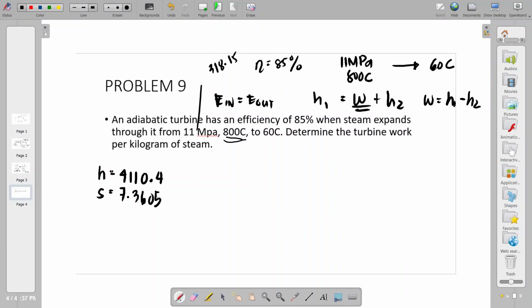Okay. Ngayon, naging 60 degrees Celsius daw siya. Okay, check natin sa 60 degrees Celsius kung anong nangyari. Table 1. Kung naging saturated temperature ba siya. Ang S dito ng 60 ay between. Ang SF niya ay 0.8312 at SG ay 7.9096. So, ibig sabihin, si state 2 ay naging mixture kasi in between siya nito. Okay? So, hanapin natin yung quality.